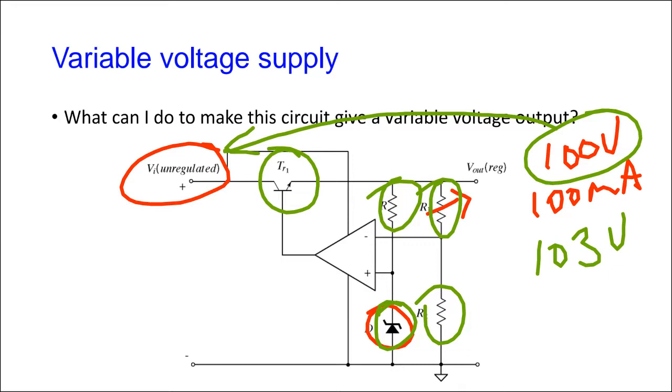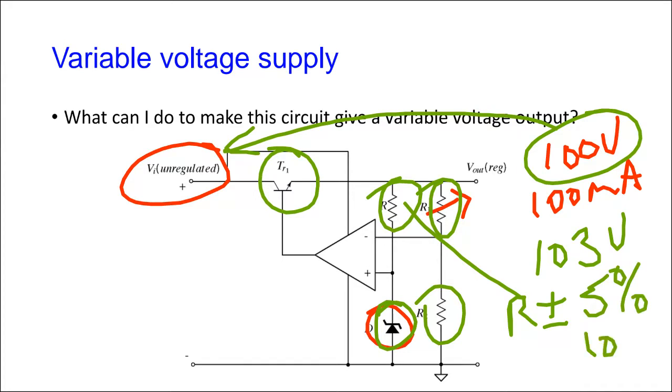Resistors carry current and therefore they get slightly warm so that the value changes. This is always R plus or minus some tolerance, right? You remember that color band on the resistor? The resistor has a tolerance, meaning that when I calculate that, it actually could vary anywhere, in this case, plus or minus 5%, plus or minus 10%, or as it gets warm, the value changes. If the value changes, the current through the Zener also changes. And because of that, the Zener voltage, remember, the Zener